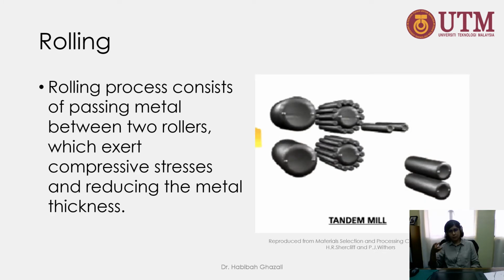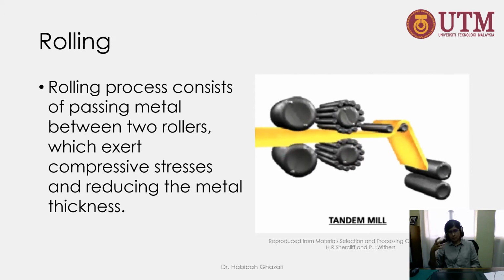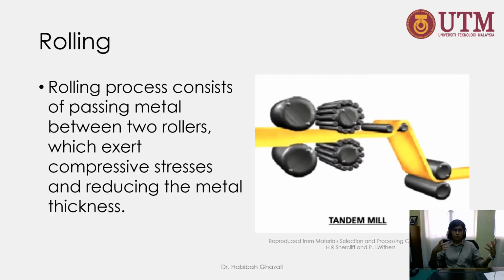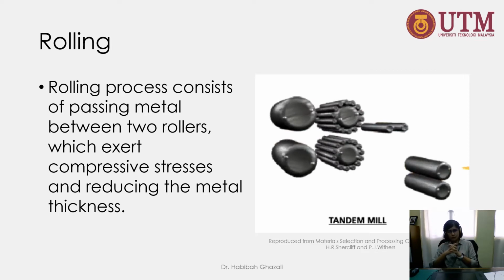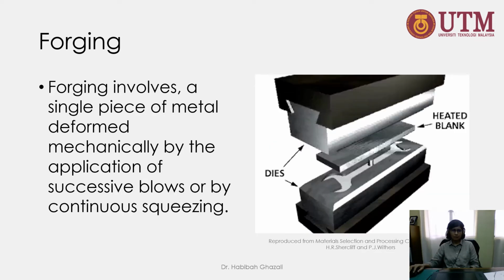What's going to happen during this process is that the grain shape of the metal, if we look under the microscope, from when it starts to when it's finished, is going to look different. This change is not necessarily going to be a good change, so we want to be able to change it back. So this is what happened during the rolling process.